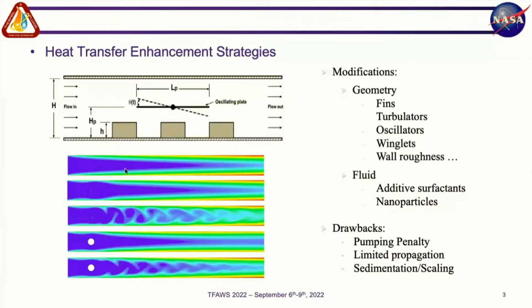Here on these 5 sketches that we have, flow along a channel. The top one is just your regular flow. You come in with a cold fluid, regular velocity, and then you see the development. You have, again, hydrodynamic and thermal development, and things that can be done to enhance that. If you just put a plate right at the entrance, you force a distortion of the boundary layer.